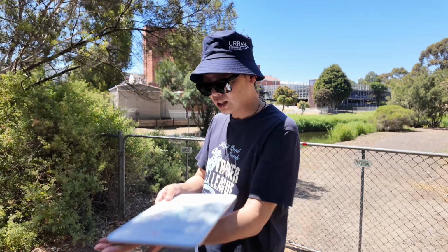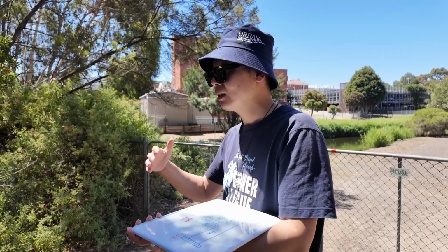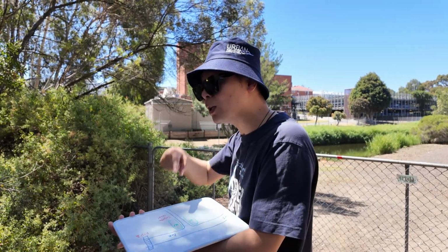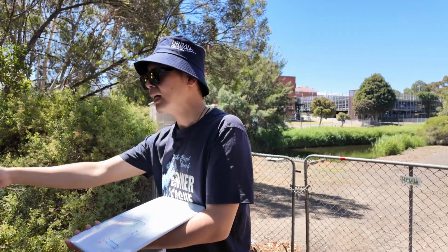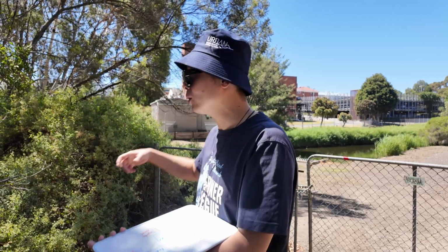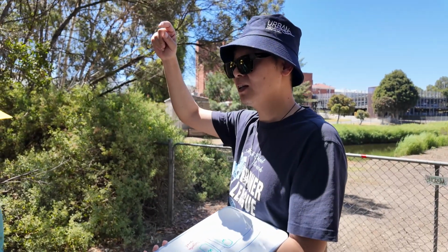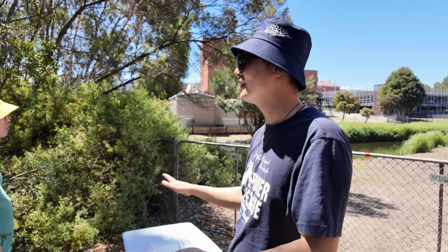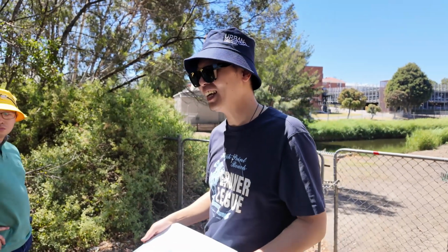So I just want to explain this again, right? In Melbourne, the creek is the drainage system. So stormwater goes to the creek. The pipes we use only take water from the urban area to the creek. And from that point, it's the creek's job to take water all the way to the sea. And that is only for stormwater. Wastewater, we build pipe all the way from houses to the wastewater treatment plant. For stormwater, we only connect the houses to the creek, and that's it. Right? So different from Thailand.